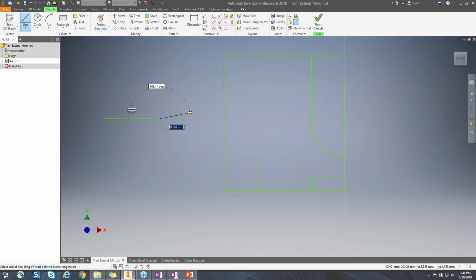The trick is if you go back to an endpoint and you left click and hold it and just drag it in the direction that you want to create that arc. And you can continue creating arcs with this. So just return back towards the endpoint and notice I'm just continuing creating these arcs like so. It's just a nice little trick here. It cuts out having to switch between commands.